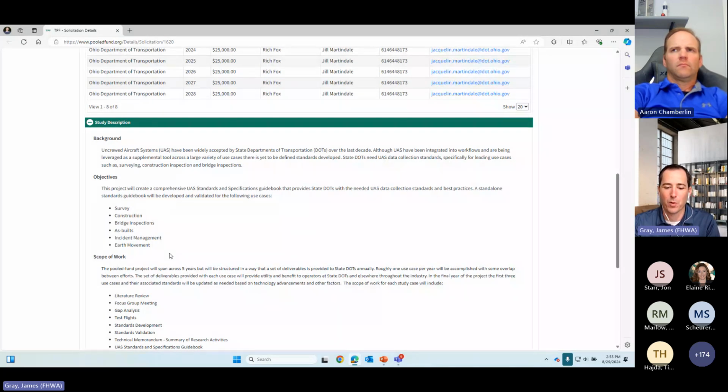So can you incorporate this functionality into measurement and payment applications? Can you incorporate this into change detection for rockfall? If you fly a rockfall area with one platform with one level of ground control points, and then you fly it again with LiDAR, the first one's photogrammetry, the second one's LiDAR, different number of ground control points. Can we cross-pollinate those data sets and actually do the change detection? Or we need to figure out what those minimum standards are for data collection. So that's the main goal of this.